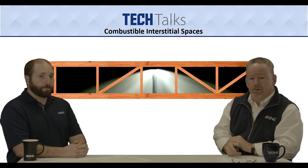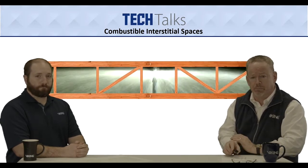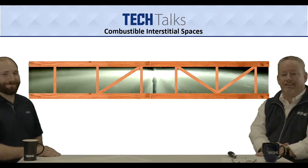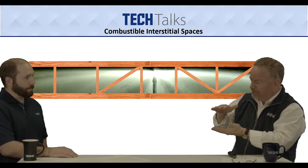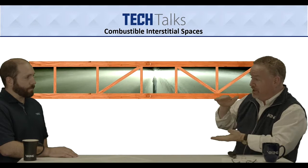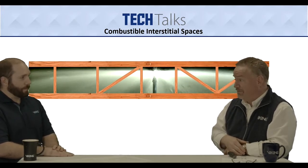Yep. So what we were able to do a few years ago is develop what we called the coin sprinkler, the combustible interstitial space sprinkler. We'll step out so we don't block this one. This has a much wider spray pattern now, doesn't it? Its whole intention is to throw that water out in a very shallow, very narrow spray pattern, developing its spray pattern in a very narrow area. Yep, correct. So we can actually cover between a 6-inch to a 60-inch space. A 6-inch space, that's even difficult to get piping into sometimes.